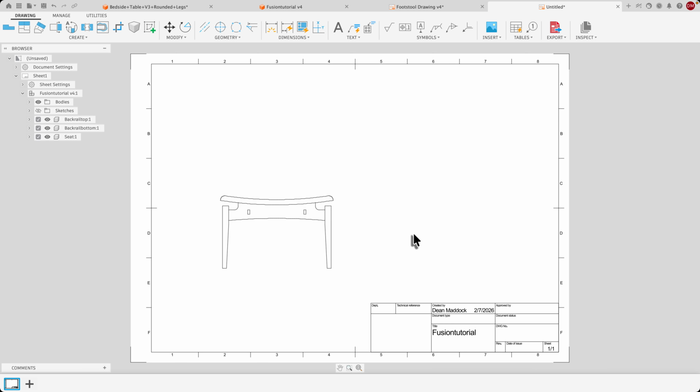Now, before I get too carried away, we've got down here this title block that I'm not a fan of, for two reasons. Firstly, it takes up too much space on the page. And secondly, it doesn't have space for things that need to be there, such as the projection symbol. So what I'm going to do is hover over it until you can see these lines appear.